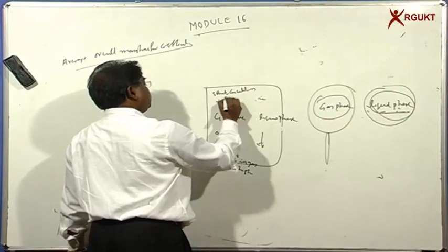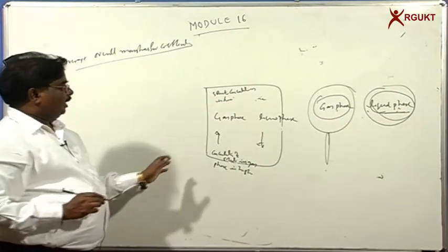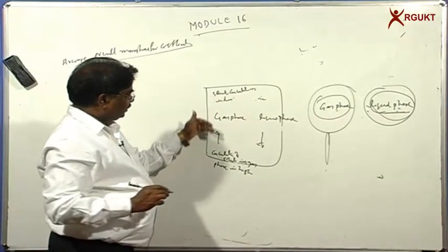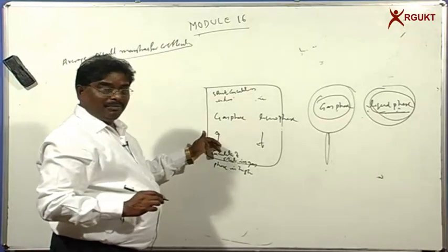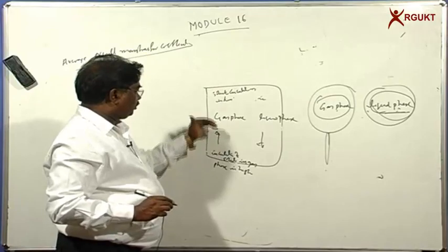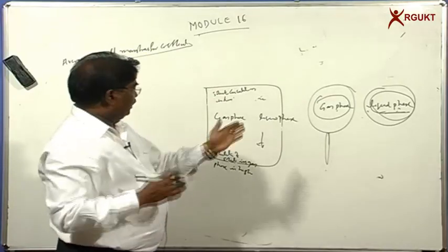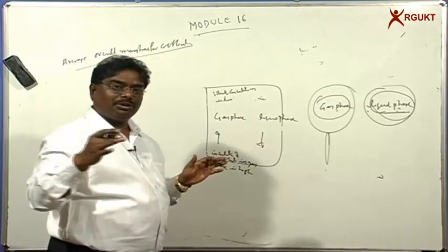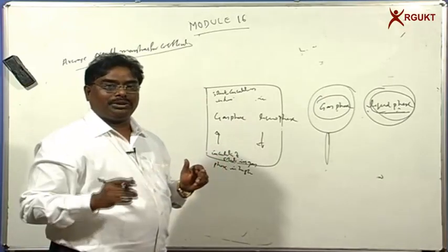In other words, the concentration of the solute is changing from bottom to top. When the solute concentration is changing from bottom to top, your driving force is going to change. Once the driving force changes, your mass transfer coefficient is going to change.